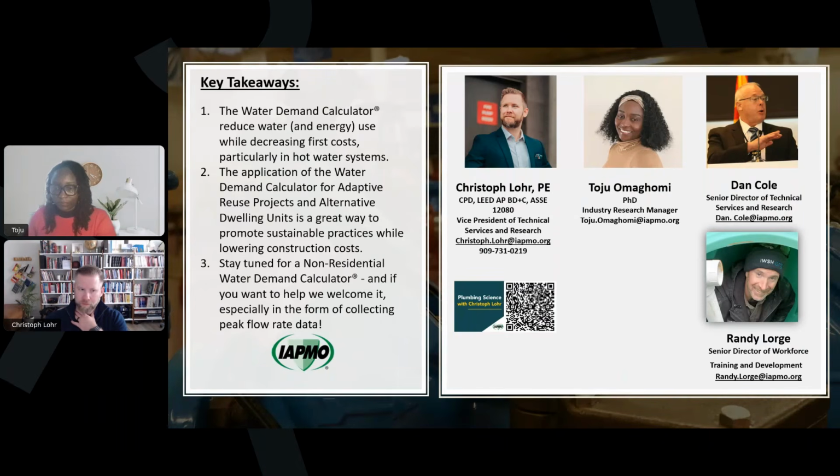So there were actually quite a few people asking if it would make a difference in the water demand calculator with the use of 1.28 versus 1.6 gallon per flush toilets. Is the fill rate still the same? Is that going to change anything? Is there anything that you would want to add to that? I'll probably ask Toju to jump in on this one, but from my understanding, I don't think a 1.6 gallon per flush toilet and a 1.28 gallon per flush toilet have a different flow rate. I think they're pretty similar. Toju, can you chime in on that? Do you recall what the data said in terms of flow rates and whatnot?